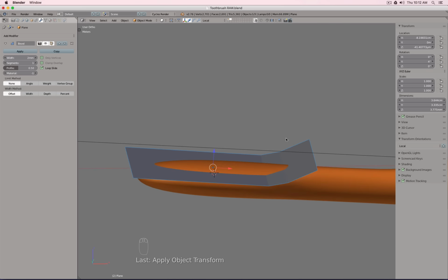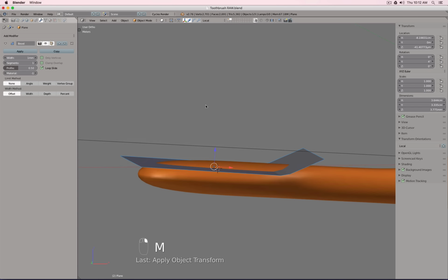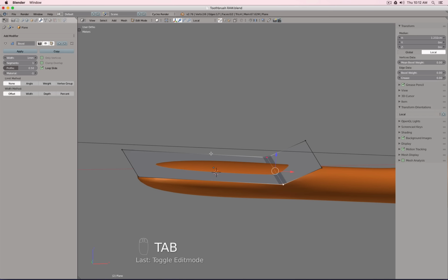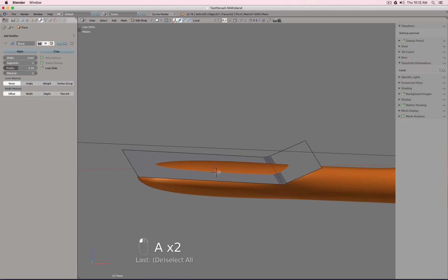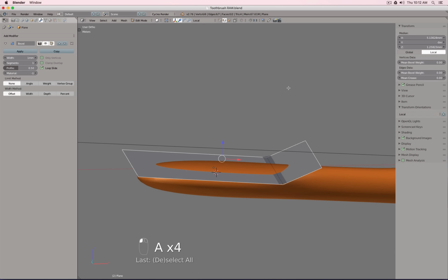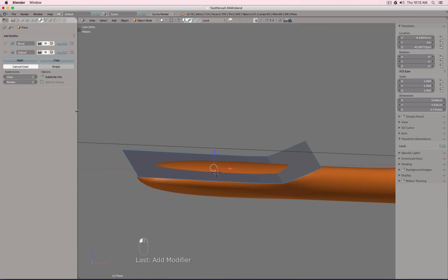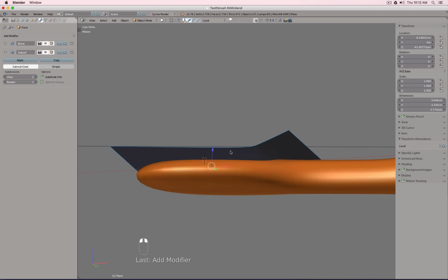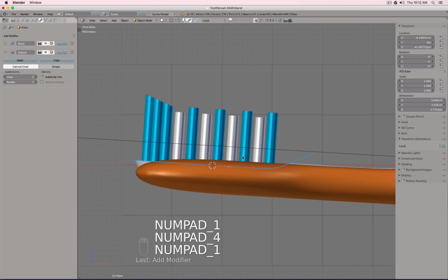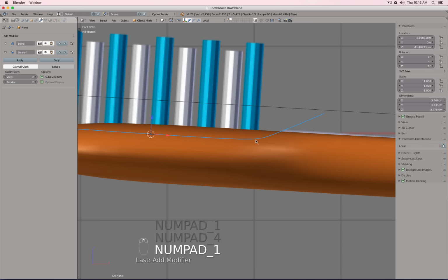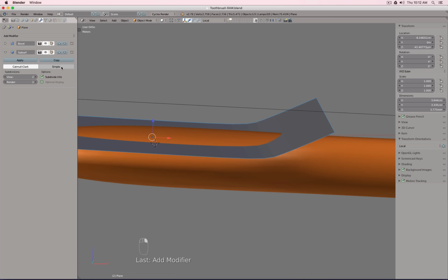So the reason why we did the bevel is simply I can break this edge a little bit, and I would like to select everything beside this edge. Shift E 1, we crease it, and after the bevel we add a sub D surface, maybe with 2. And you see actually this bevel sharpens this edge by adding a kind of loop cut, and in this way I can crease this one a little bit more predictably.